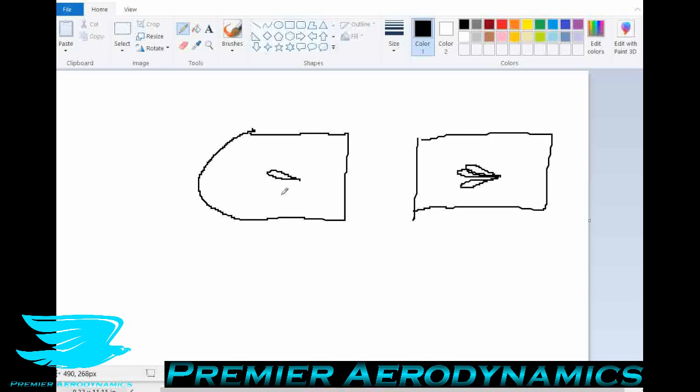With this approach with the C grid, all we have to do is just say, okay, the air is coming in at different angles. And because we have this corner, the bottom corner here, it meets quite nicely with the wall, the side. We don't have to worry about flow separation around here. Whereas if we were to do the same thing with the rectangular CFD box, if we were to put an angle of attack like this of the air coming in, the flow would separate around this point and we'd get quite a lot of problems with the boundary conditions that we're specifying with the sidewall here.